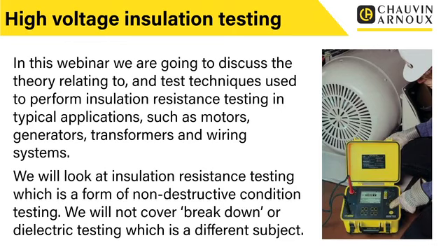Today we're going to talk about the standard applications, things like motors, which we will talk about in quite a lot of detail. Although we're using these applications as a context for our session today, insulation resistance testing is a very wide topic. So we'll look at insulation resistance testing, which is a form of non-destructive condition testing. We will not cover breakdown or dielectric strength testing, which is a different subject. So very important, what we're talking about today is non-destructive condition testing.